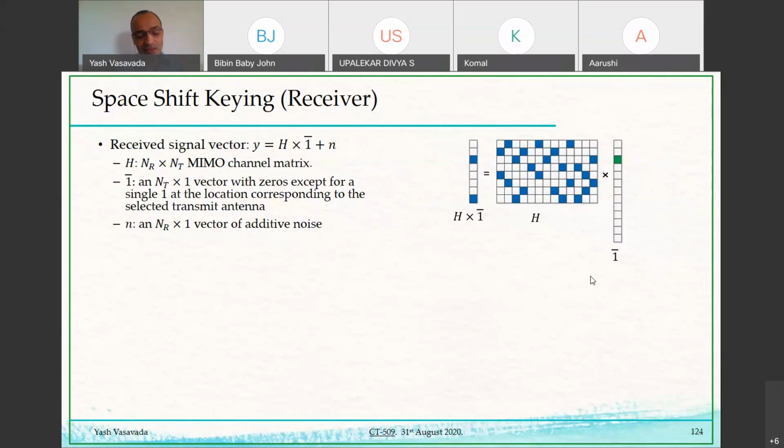When we transmit QPSK or 8PSK, the difference is that in QPSK our transmitter has a set which has 4 members. In 8PSK, the transmission set has 8 members. And so that is why 8PSK allows us to transmit 1 extra bit of information every time we transmit one of the 8 symbols of 8PSK compared to one of 4 symbols of QPSK. Again, the actual form that the symbol takes doesn't matter. In space shift keying, our symbol is actually an antenna, in fact. It doesn't look like a QPSK symbol or a letter of the alphabet or anything. So now we have something which is our symbol.